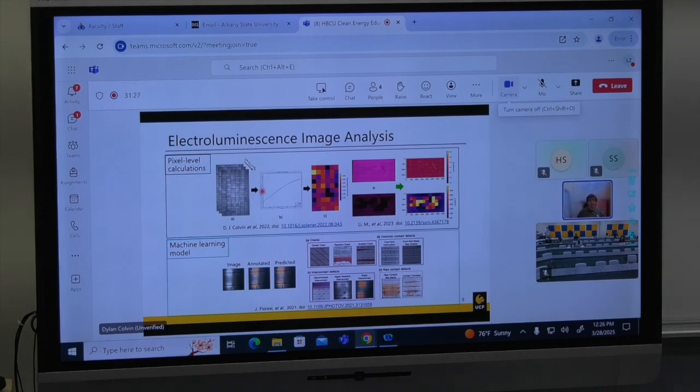Well, you can get that dark current voltage curve for every one of these cells, not just the panel, just by taking a series of electroluminescence images. You can use the brightness levels of each cell as a way of getting the voltage that cell is operating at. And using the current that you're applying to the panel, we're assuming for all cells in series, same current through every cell. Now you get a voltage. Take a bunch of images, and now you've got this nice curve that you can analyze and start getting some performance characteristics out of.